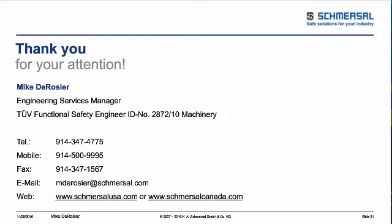But when you look at things like control category 3, category 4, or control reliability, part of what's happening in the overall safety system is they're being dynamically checked every time you actuate them. Other safety functions such as e-stops. E-stops you typically test more or should be testing more than the actual need. Hopefully you'll never need an e-stop. So there's nothing in any standard that I'm aware of that specifically states this, but a lot of times we may give a recommendation of testing e-stops once or twice a month to make sure that they're functioning properly.